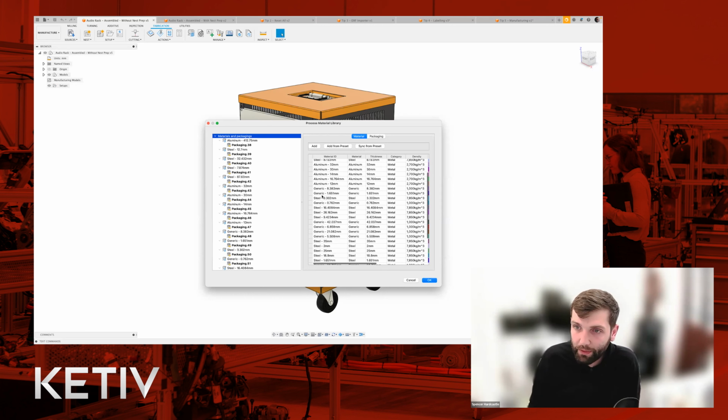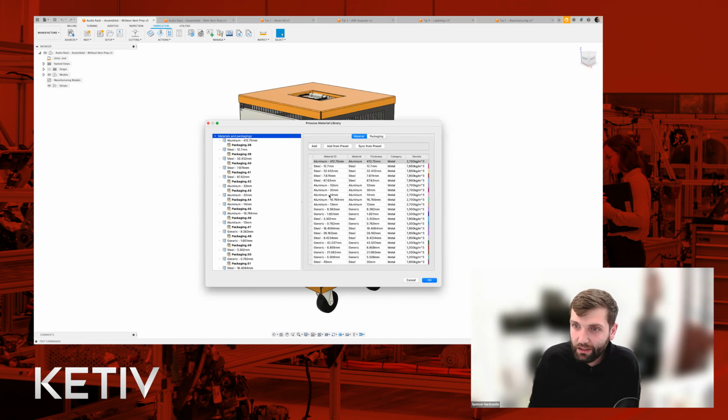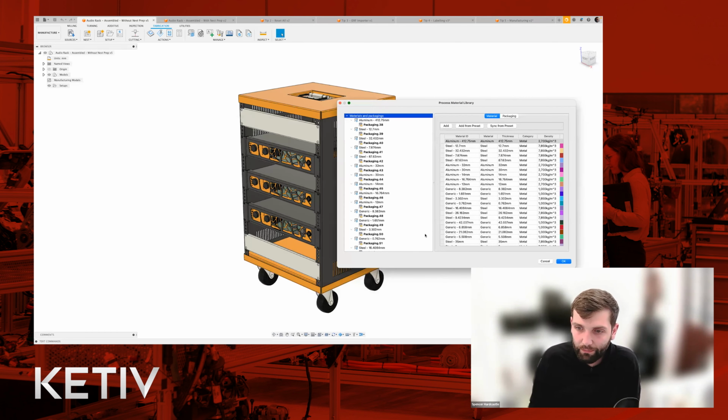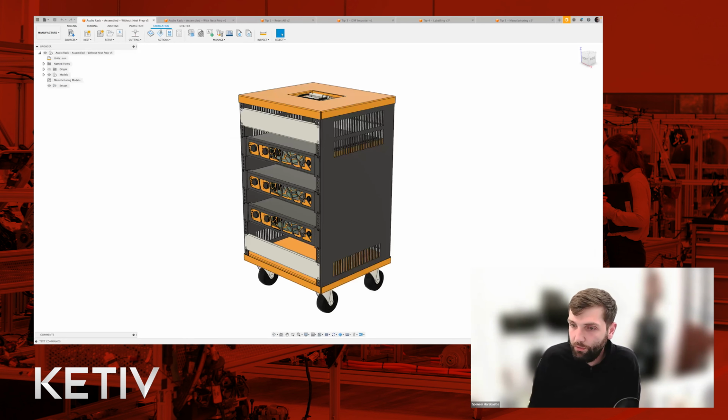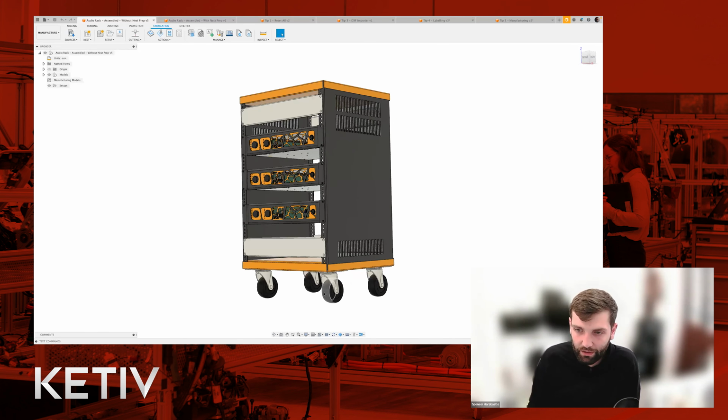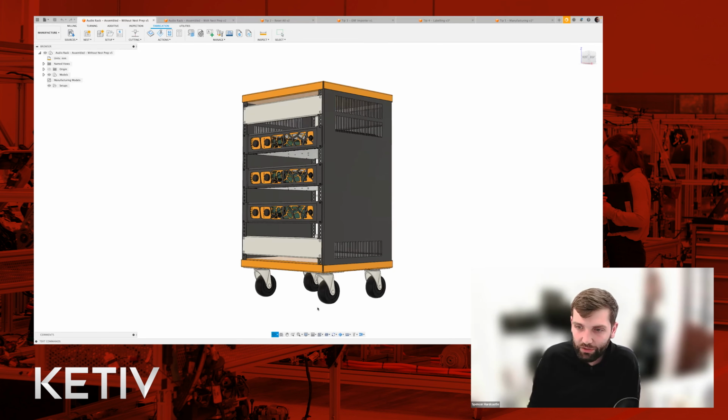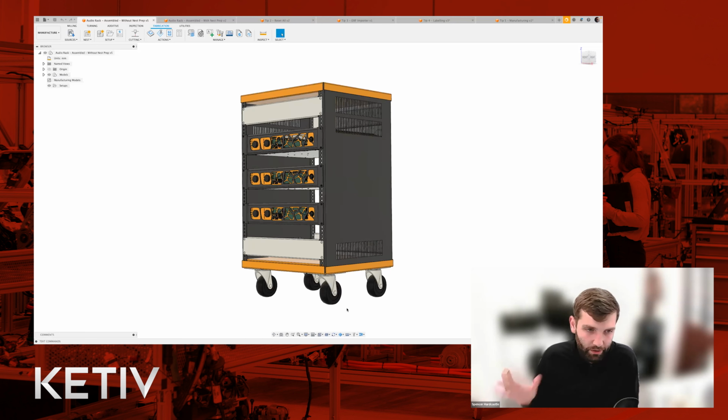And what it's picking up there is, and there's an 87 steel there. It's picking up things like the wheel. So let's look at this caster, right? If I was nesting that caster, it's obviously going to choose this face on the end here as the planar face, the nestable face. And then it's calculating the thickness of the material perpendicular to that. So you're going to end up with rubber that's really thick. And that's going to live in your library forever.